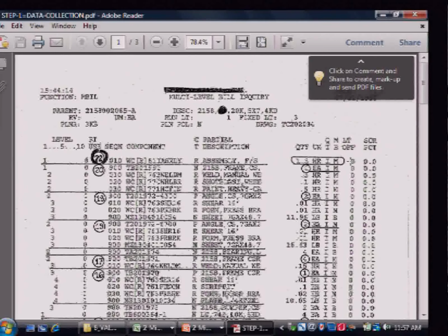You need industrial engineers on staff who will essentially record all of these items of data that effectively appear in the process box on any value stream map, where for each process step you're trying to capture changeover time, cycle time, first time through, uptime, cycle efficiency. Is it 100% labor operated, or it's partly automated, partly manual? There's no reason why these fields in your ERP records could not capture all the information that today you're being told, go on the Gemba and observe and then collect the data.